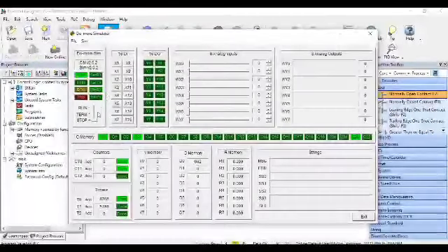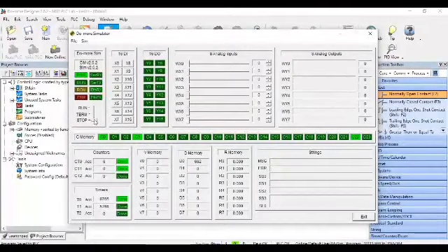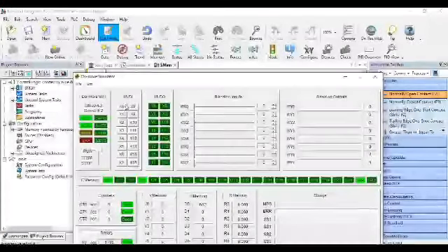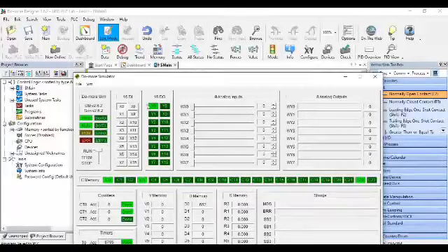The first step you have to do is always turn on your PLC. So I'll click run. So what should happen is if I press X0, Y0 turns on. So this is a simulation of the switch and bulb example. If I press my switch, then output is on. If I disconnect the switch, the lamp or bulb is off. So you can visualize this in the simulator.